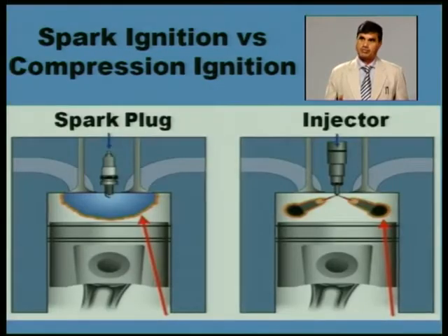It can be more than 1000 bar. Droplet size is also very small, because the size of the holes in this nozzle is very small, say around 0.2 mm, very small holes which are not even visible with naked eyes. So through these holes high pressure diesel is injected into the cylinder.